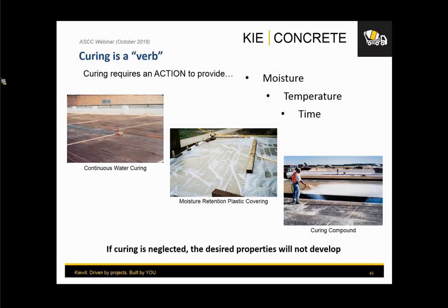But when you're dealing with a concrete that is not going to be exposed to critical conditions like the de-icing chemicals, but you just want some level of protection from the material drying too fast, then obviously you start looking at other options like moisture retention, and curing compounds can be used in some cases. For a strength purpose or not, the curing is all going to be affecting the very, very skin, right? So if you think about it, the skin of the surface is the one that's going to be mainly affected by the curing.